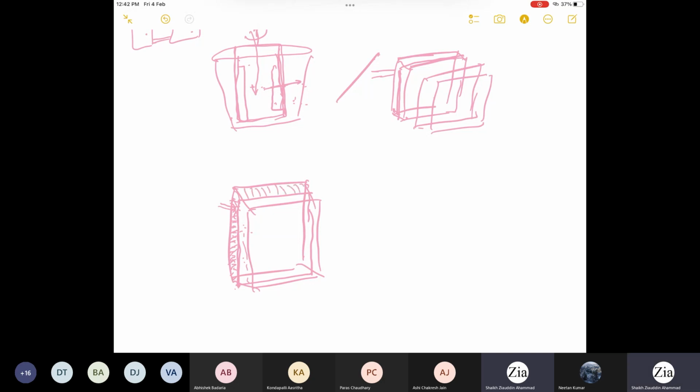When the entire space is occupied by the cake, you stop the operation and dislodge these frames. That means you dismantle the frame, remove the cake from one side, and then reassemble to get the operation started again. So again, this process is also a batch process.